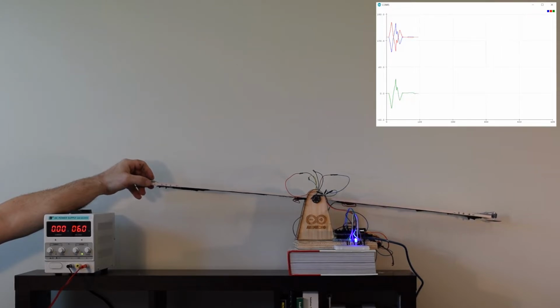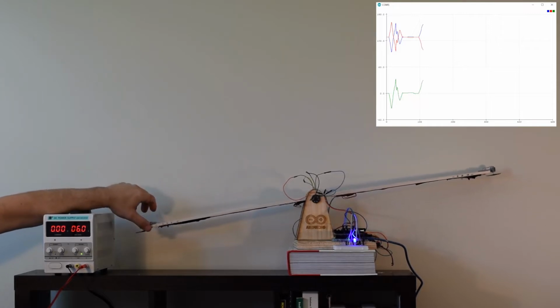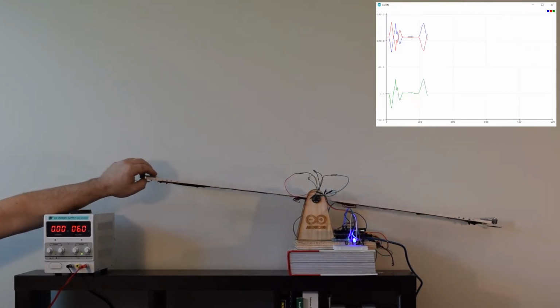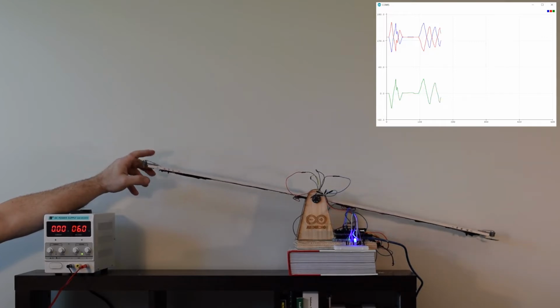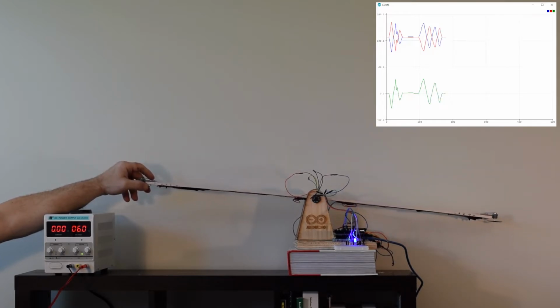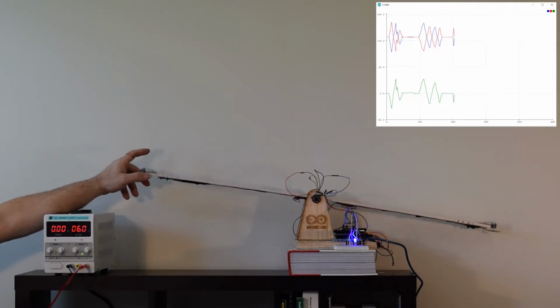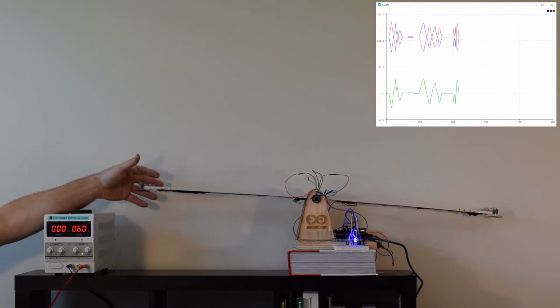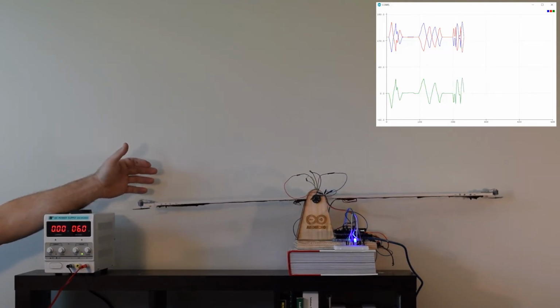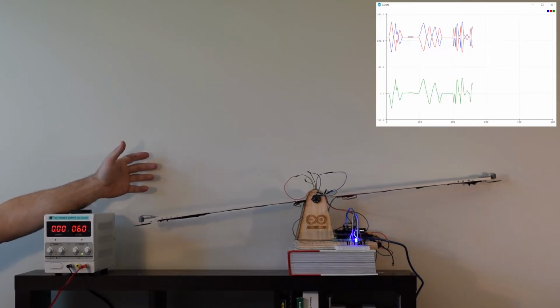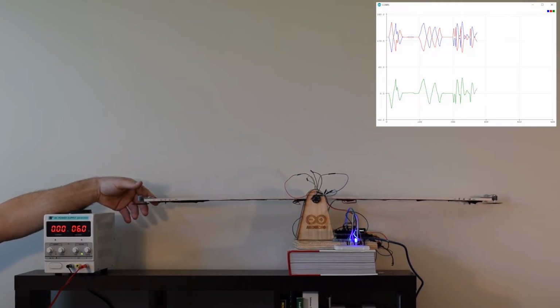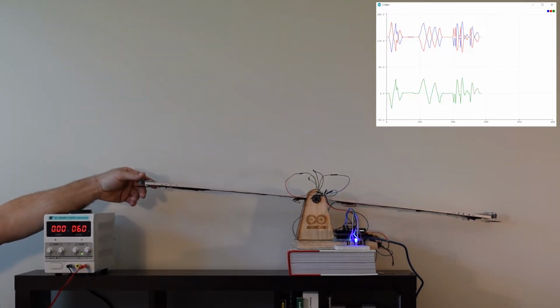I printed the input PWM signal to both motors and the output value from the PID equations to the serial plotter oscilloscope. The graph shows motor 1 in blue, motor 2 in red, and the output from the PID equations in green. I could see from the graph that the motor base speed was indeed set to 128. The output signal to each motor was reflected along the base motor speed axis, and the output signal was accurately added to motor 1's base speed and subtracted from motor 2's. The graph confirmed that both motors were indeed receiving the correct PWM signals and allowed me to diagnose the lazy motor.